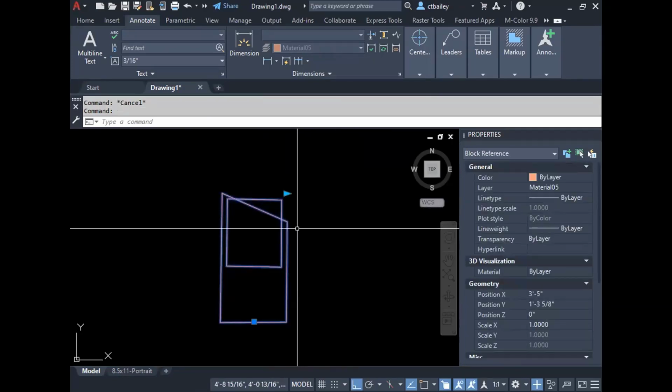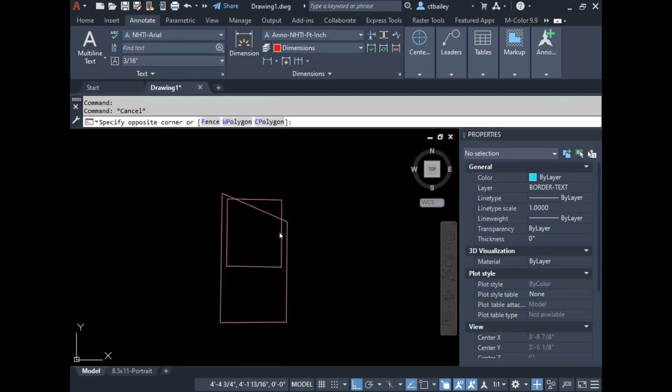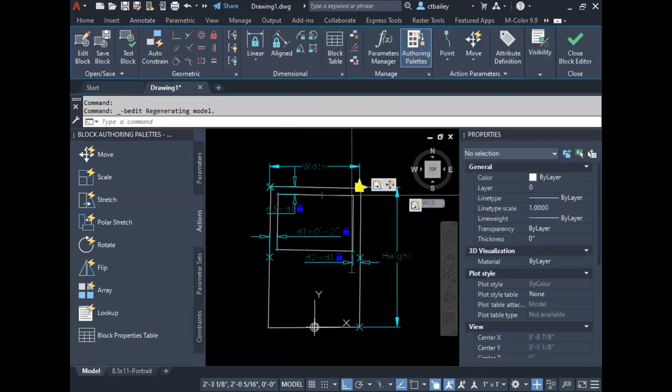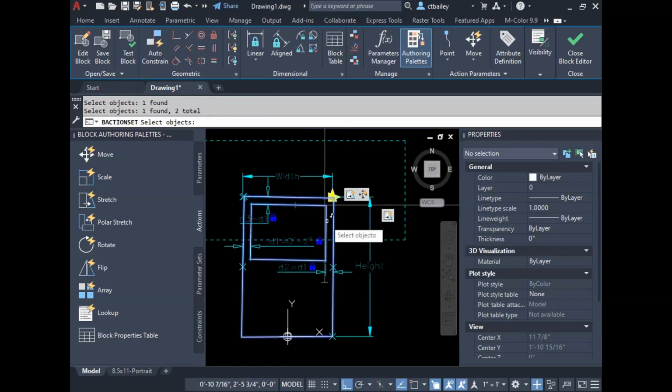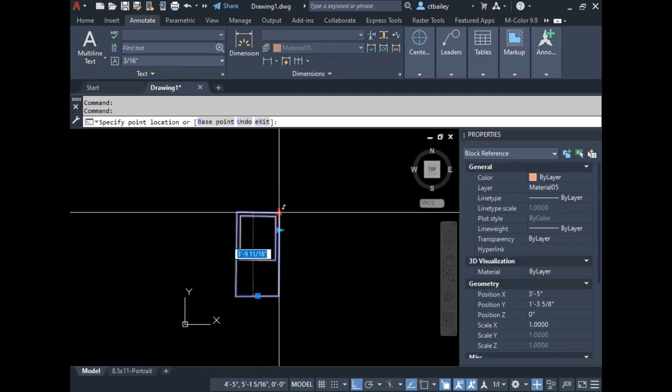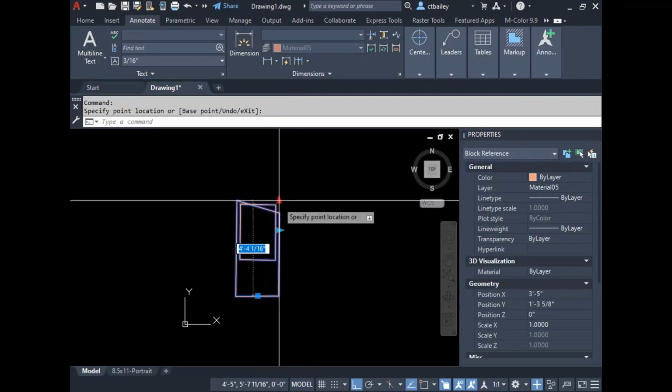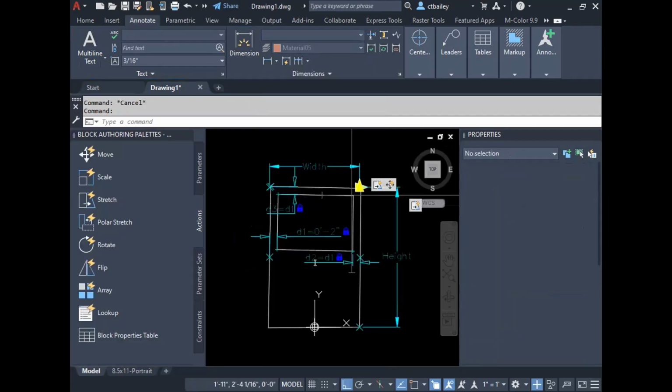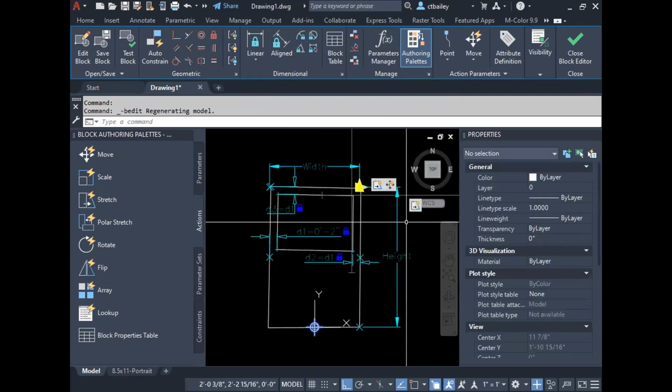My drag is now working on the inside window. And I've got to check to make sure that the drag is still working. We're going to action set. I'm going to do a new selection set, new frame, pick the outside, pick the inside guy, and pick the height parameter itself. And close. There it is. Oh, there's not. So it takes a little bit of effort to get these to work. But when you get it working, it's amazing.